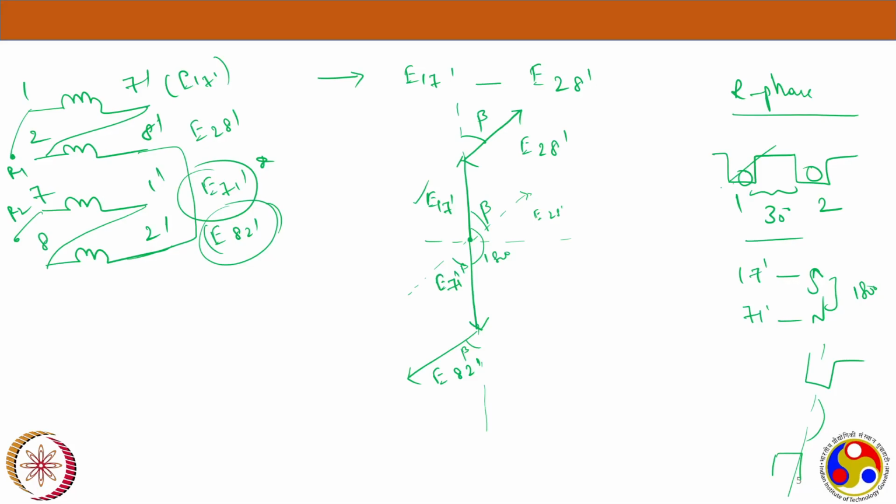Now see, this is not connected. These are the phasors. Now, if somebody by mistake adds all these phasors, what will you get? If I have not paid attention to the positive and negative here, I just connected all the four coils in series, like this. So this phase and this phase is also a series connection. This is not a wrong connection, but I just didn't pay attention to the voltage terminals. Where is positive? Where is negative? I didn't pay any attention.